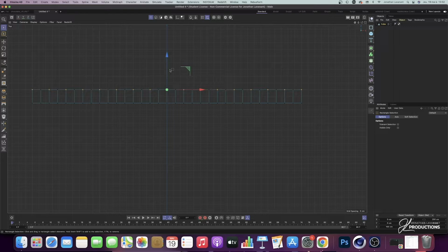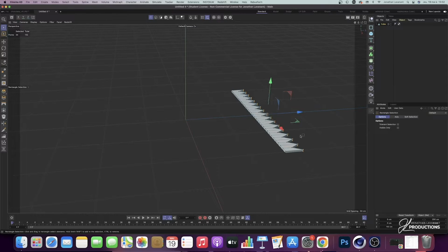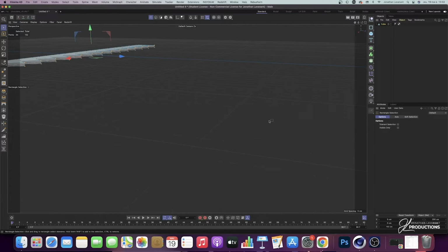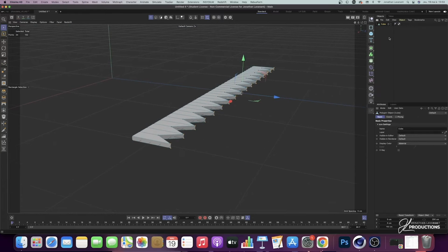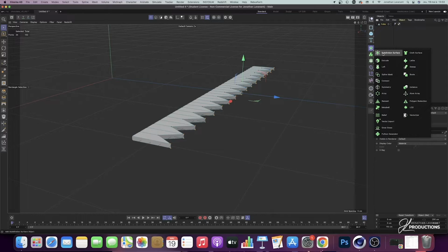So once it's finished, I'm still translating on the blue axis, so the z-axis, so I'm going to do my translation. I press shift and there I'm going to put 10 centimeters, here will be more than enough. Then we can come and add the surface subdivision, so who is right there that I just selected. I press Alt and I let go as it comes directly to the cube.